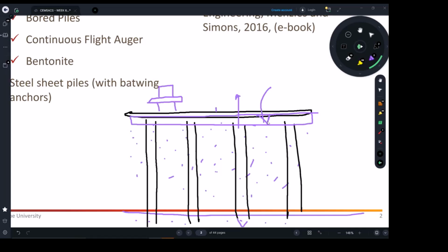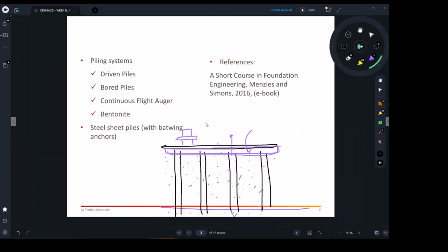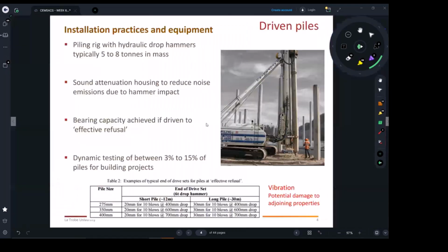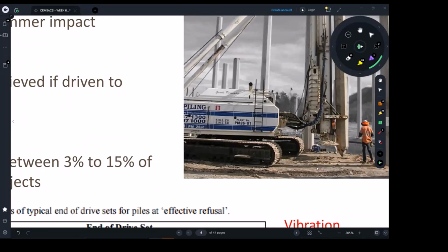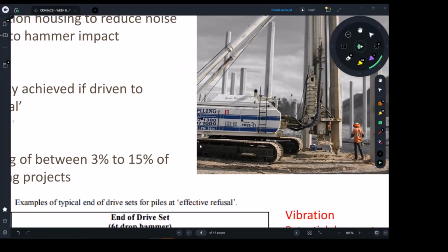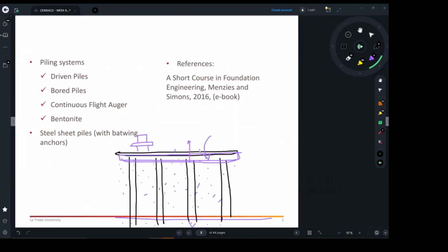Remember in week 1, we talked about different types of slabs. We talked about banded beam slabs, flat plate. Basically, this is a flat plate because there are no beams or band beams. So it can be as thick as 300 or 400 mm of concrete slab sitting on piles. And that's really what's happening in this picture. At this stage, they are just nailing down those piers. Now, I was talking about columns.